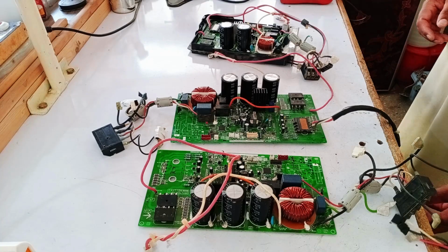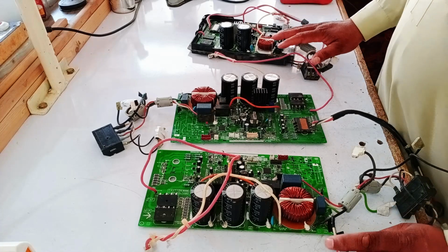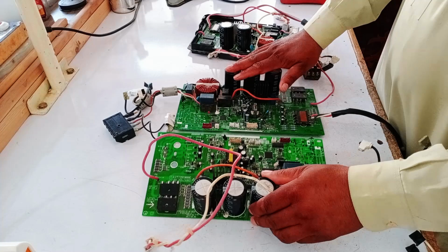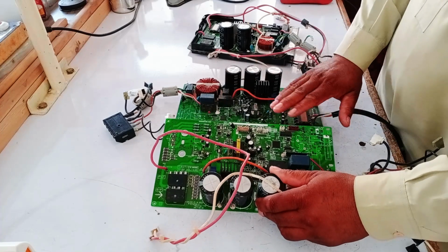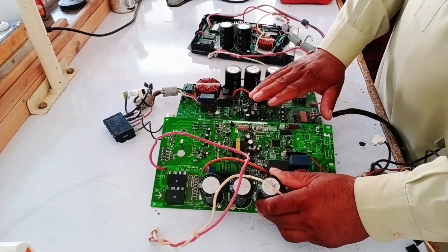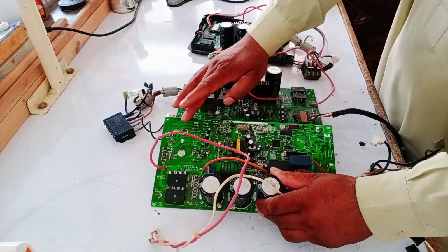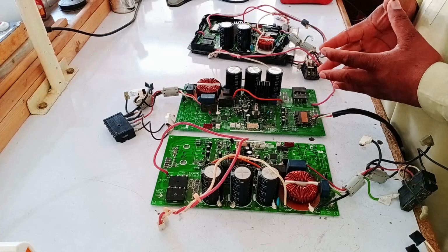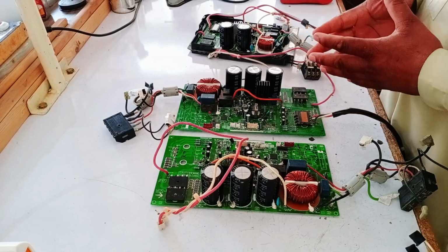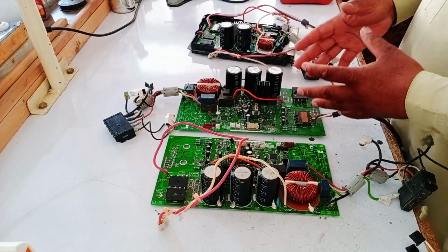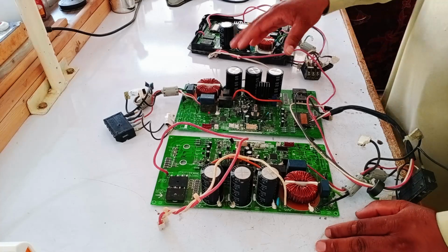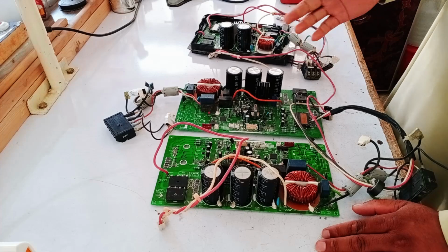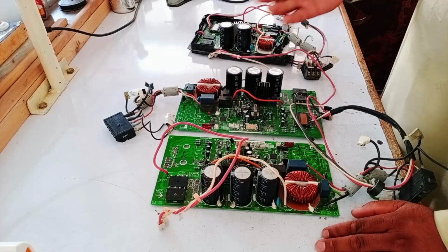Now we will explain what could be the reason when an error appears in a 1.5-ton, 2-ton, or 2.5-ton unit. As you can see here, there are 3 PCBs placed. This PCB is used in a 1.5-ton unit, and this one is used in a 2-ton unit. The first fault usually occurs due to fluctuations because the unit stops working while operating, which then triggers an error. This fault is temporary, so first, check the electrical supply. If the electricity is stable, then inspect the unit. There is a chance that after a fluctuation, a single blink appeared.